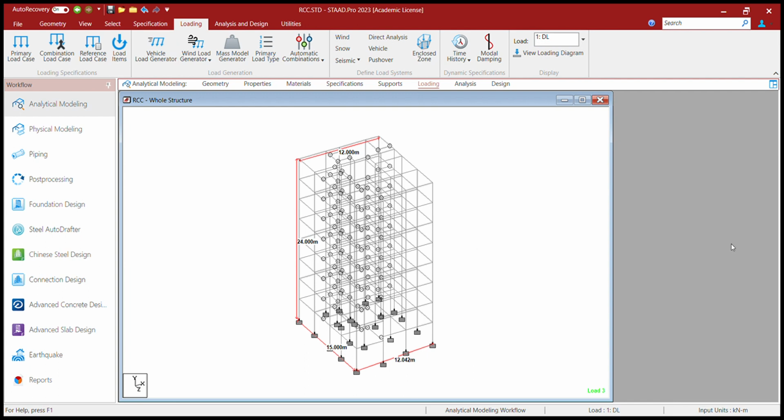So it is close, add. Now here generate 2015 structure type rectangular clad. Height it has taken, interval that we need to edit it, that is 3 as per the building given. Select the city Nasik. It's 24 total height. Total height is 24 with the interval of 3 meter. Select city, it is Nasik. Risk coefficient factor, right now we will just assume it 1 accordingly.